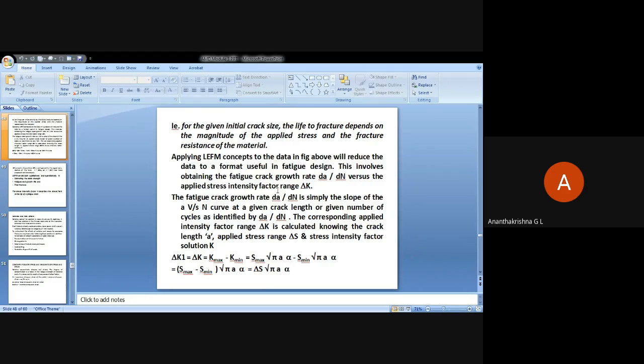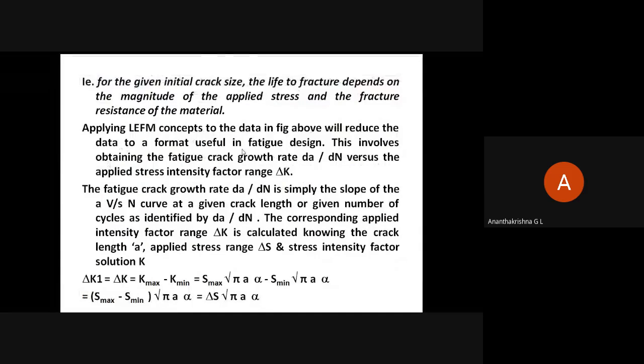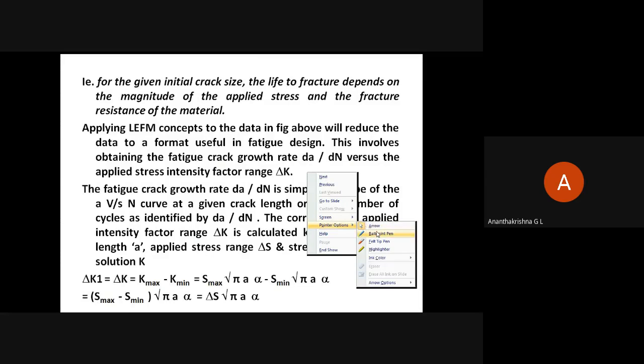So we apply the LEFM concept to do fatigue design. For this, what we need is the crack growth rate delta A by delta N versus the applied stress intensity factor range delta K. Delta K we can obtain using the equation here, that is S max minus S minimum into root pi into A into alpha,